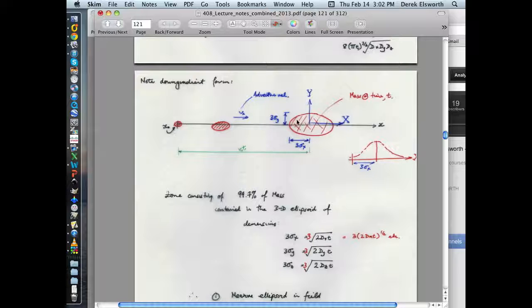And so what we could do, since we know that the dispersion of this plume is a function of these 3 standard deviations of the Gaussian distribution, if we can find the edge of the plume and we can measure exactly what this length is, we have a chance of being able to figure out exactly what the dispersion is. And we hope that because it's being driven by the natural gradient, which sits in situ anyway, that if we measure this and we know what the plume looks like, then we can pull this value out of it just by solving this equation. And that's really all it is.